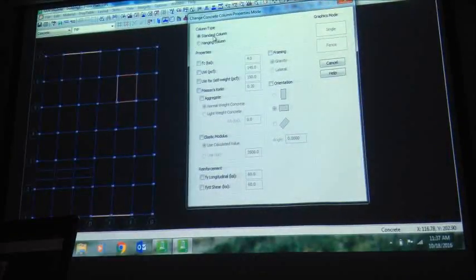Click on that and a dialog box will come out. Standard column is fine. In my framing part, I click on that and change from gravity to lateral, and I will do a fence so that these 4 columns are lateral.